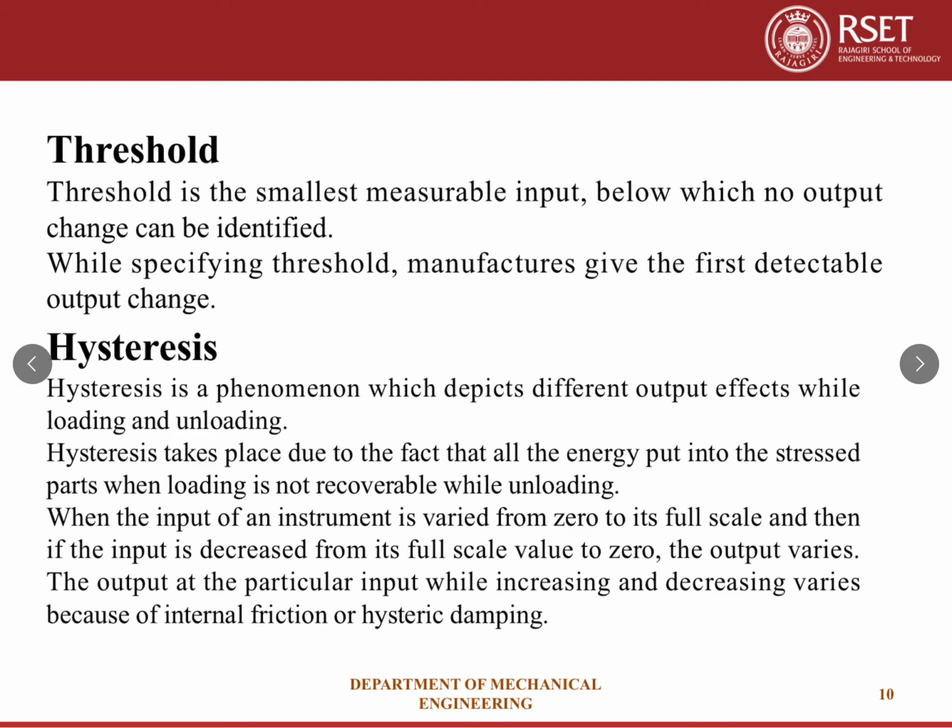If we gradually open the valve from 0 to the maximum and take the flow reading at a particular valve opening, we get some value. Then we reduce the flow rate by closing the valve from maximum to 0. At the same valve opening, the discharge reading will be different. That is due to hysteresis.